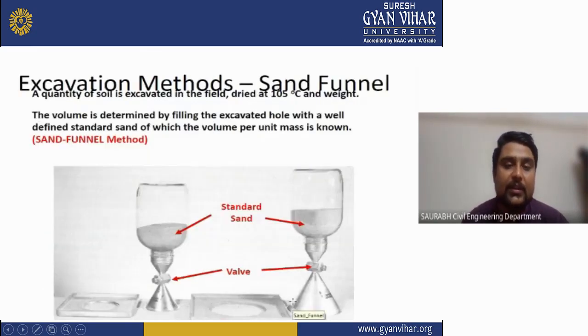Now we will see the excavation method by the sand funnel. The quantity of soil is excavated in the field, dried at 105 degrees Celsius, and weighed.